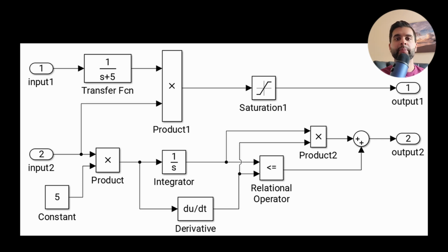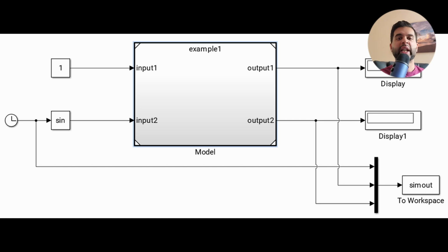Here is my test model. One thing you need to understand is that every time you compile something from Simulink to C++ or even MATLAB code, you have to test it end to end because there are bugs in Simulink Coder which you will see. And this will also vary based on the version of MATLAB that you have, right? For me, I did this on a very old version, I think 2015B. So it won't be the same as the new versions, which are much better and bug-free. But in all cases, you still want to test it every time.